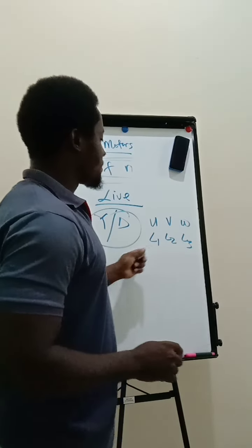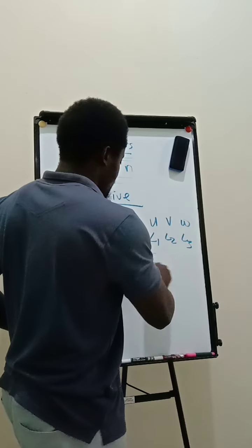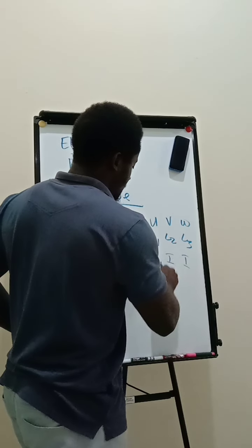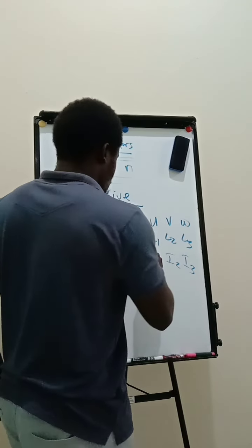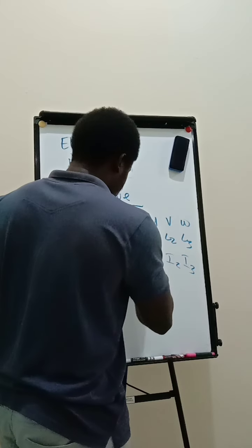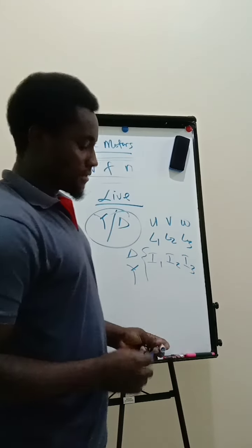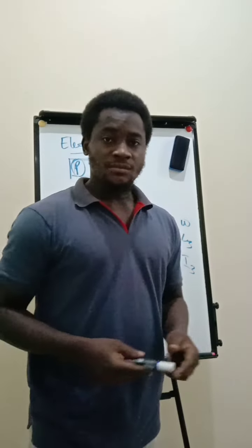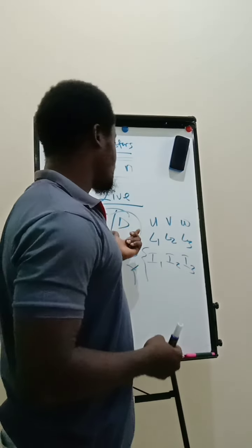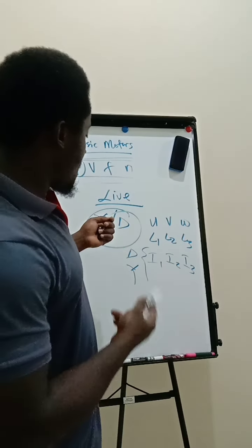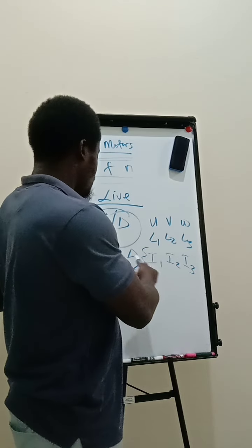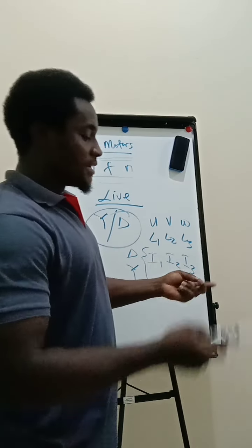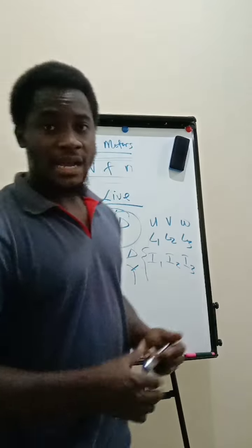Take down these different currents, I1, I2, I3, in star and in delta. Then give power to the electric motor by supplying it in star delta starter, and test the different currents in star and in delta using a clamp ammeter.